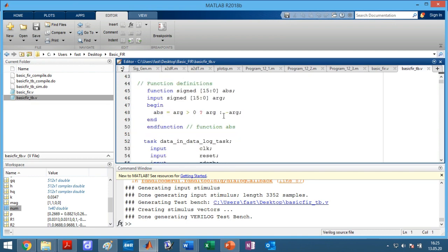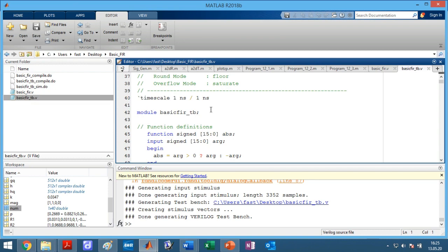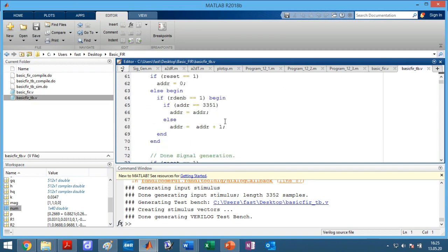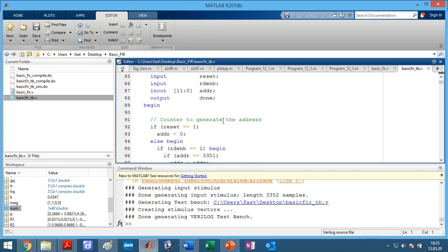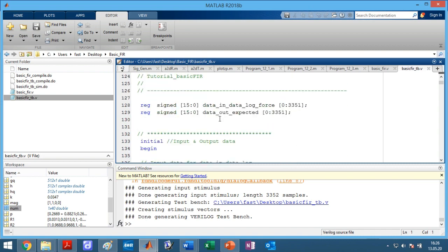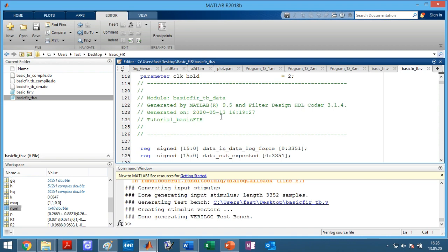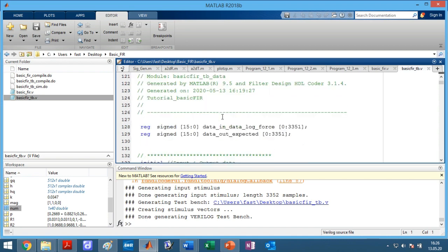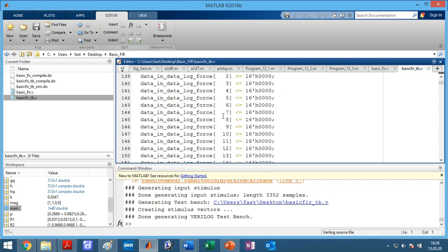You don't need to specify the inputs directly, and this test bench will generate the signals clock, reset, clock enable, data in, and will pass them to the module. Based on this we can simulate that design and record the output of this filter to verify whether the filter is producing correct sample values or not. So we will learn this in the next lecture using Modelsim.